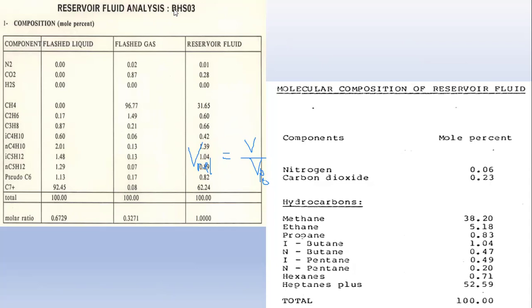Those samples usually account for those impurities, both from the samples taken from the surface and the bottom hole samples? Yeah, it's been accounted for because it's within the fluid column. For example, in the surface sampling, nitrogen, CO2, and H2S all come in the form of gas. So definitely they will be within the gas column, the gas you collected. It might be more of hydrocarbon gas, but you will definitely have them dissolved in it.